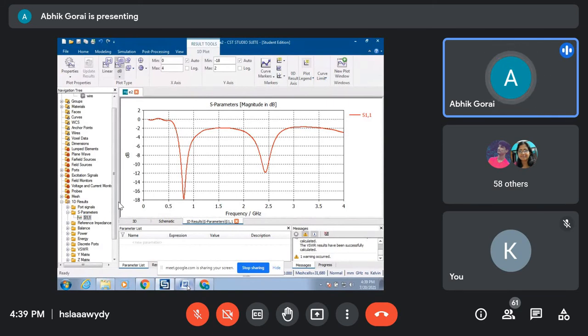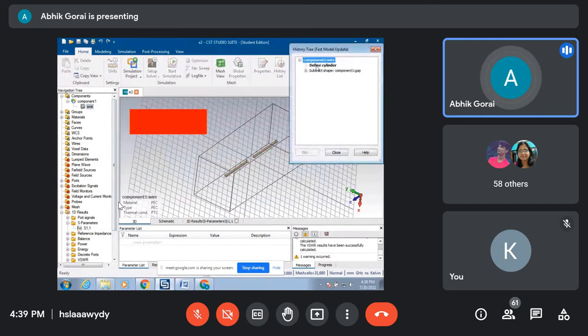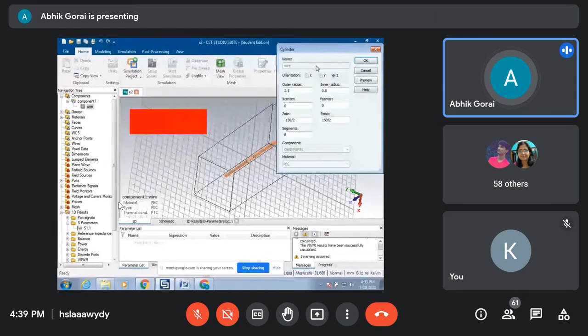Okay, so it is seen that if I take it to be 120 mm, that means a little less than 0.5 lambda, then your resonance will be perfect. So instead of 150 by 2 and 150 by 2, let me take 120 by 2, such that the length of the dipole is 120 mm.